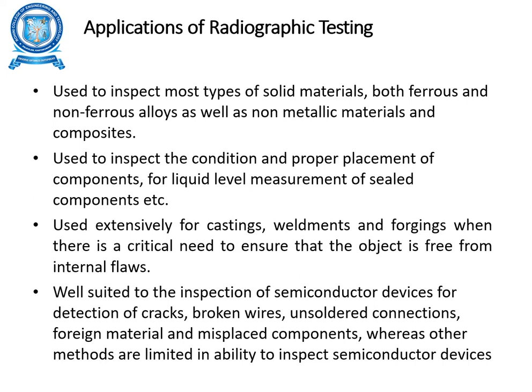It is used to test castings, weldments, and forgings when there is critical need, to ensure the object is free from internal flaws. For semiconductor devices, it detects cracks, broken wires, unsoldered connections, foreign materials and misplaced components, whereas other methods are limited in ability to inspect semiconductor devices. You can go for radiography testing.